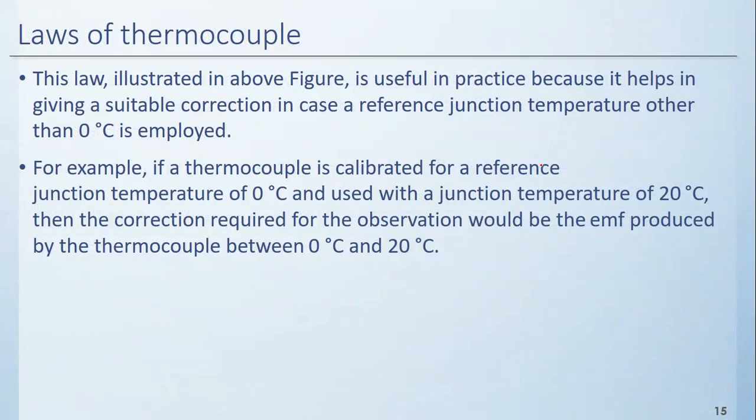Now the application of this is when you are using a thermocouple calibrated for a reference junction of 0 degrees, and you are using it for a reference junction of 20 degrees. If so, then the correction can be done by subtracting the EMF produced by the thermocouple between 0 and 20 degrees.